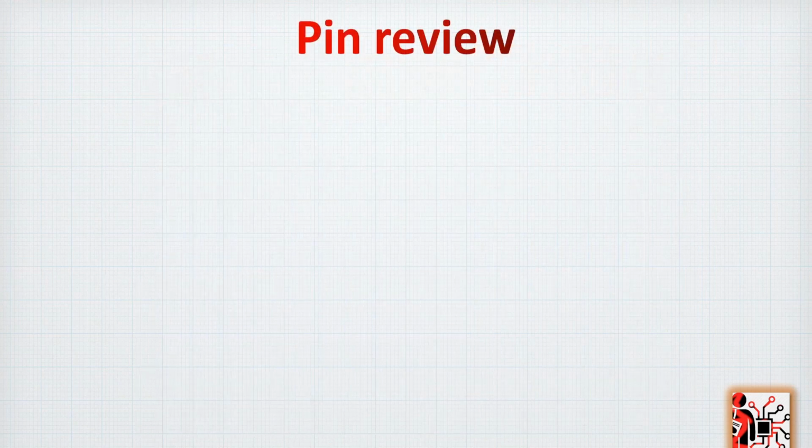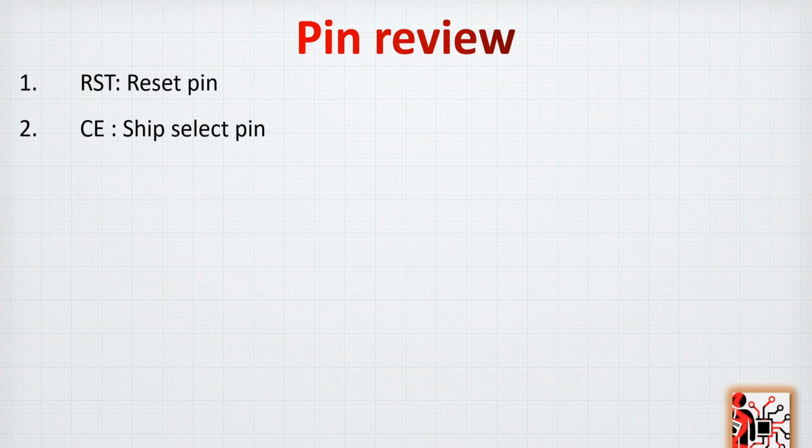Let's take a pin review. The first one is RST, the reset pin, quite simple. The next one is CE, or chip select pin. I don't know what CE stands for, but it's the one that will be connected to the chip select of the SPI. The third one is DC. I'm not sure what the D stands for, but this is the control pin. We will see more later in the datasheet of the screen about how this is going to work.